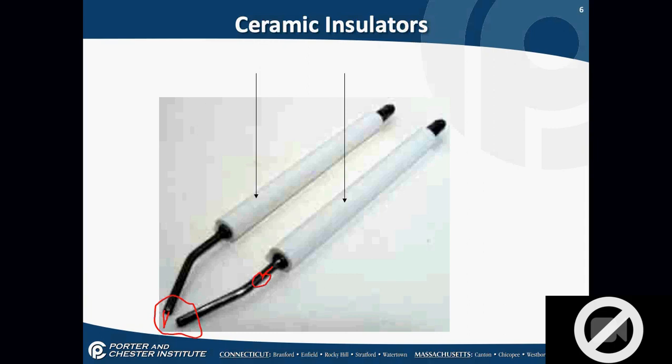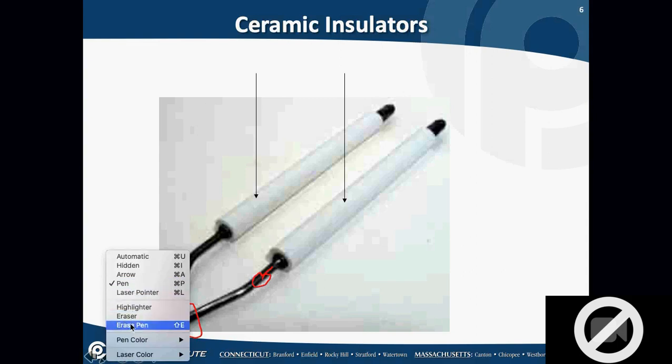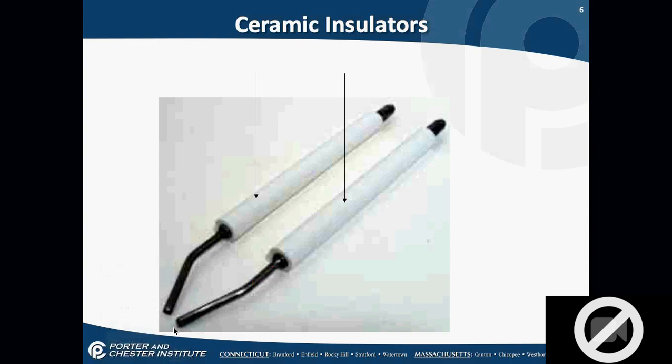Well, two things happen. First of all, if you don't catch that these have worn out, the distance between the tips is starting to get wider. So I'm going to have a weak spark. Now, if you came into a service call where you had to adjust these back into place, it gets very difficult to get these two corners, like right there and right there, to be the same correct distance apart.